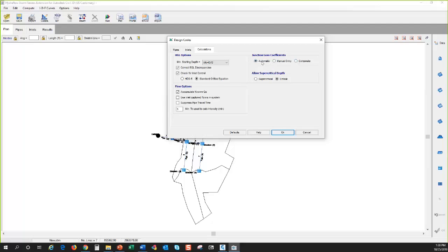I'm looking into the exact calculations for this automatic method. I've requested that information from Autodesk. I've requested information on the composite as well, and I got information on that. That is based on HEC 22, the composite method in addition to the second edition, not the third edition. So this is based on HEC 22 second edition, this composite method.